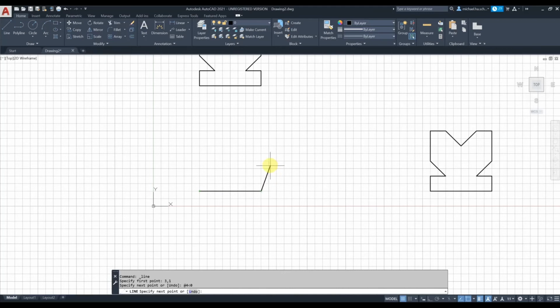So let's go ahead, add sign, so it's relative. So previous point, the length is 1 and the angle is 90 degrees with respect to positive x direction. Okay, add sign again, length is 1, angle is 180 degrees with respect to positive x direction. That's in this direction, right, to the right side.